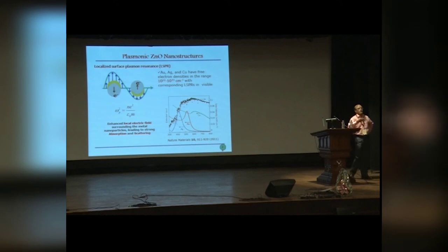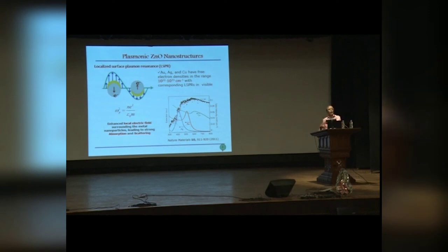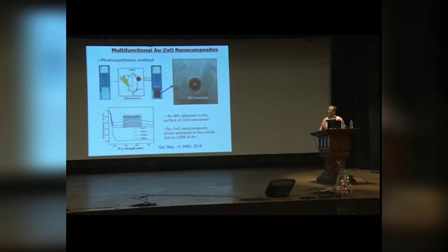The other thing that we took are the zinc oxide nanorods, in this case either nanorods or nanocones. Obviously plasmonics is very well known: if you decorate it with different metal particles, you get strong localized surface plasmon resonance, and that gives rise to enhanced absorption of the light or enhanced scattering or trapping of the light. So if you can use this for making devices, I will show this is the synthesis method.